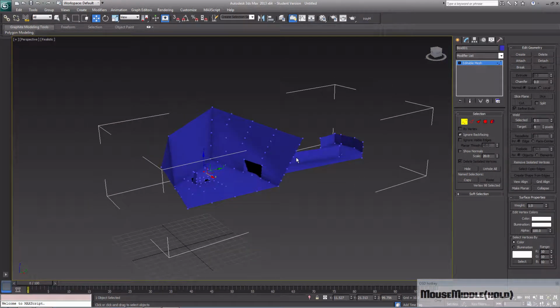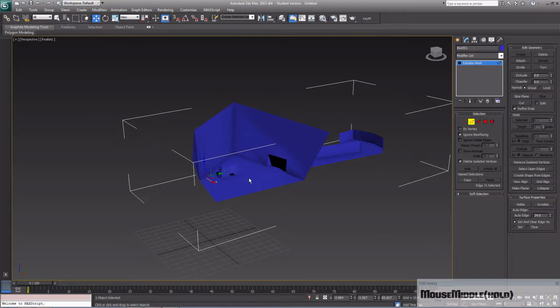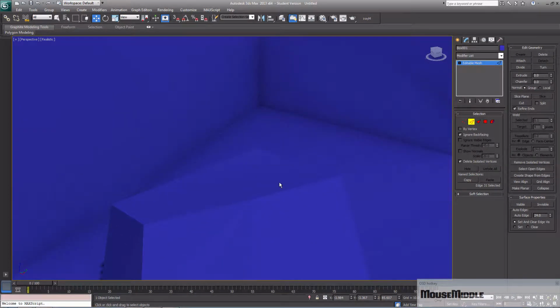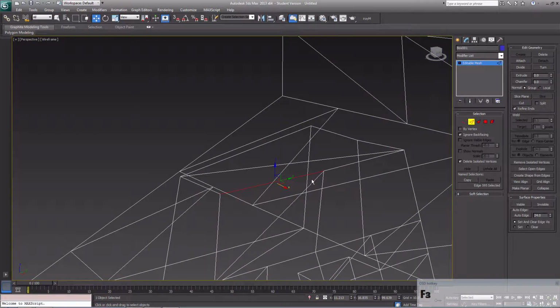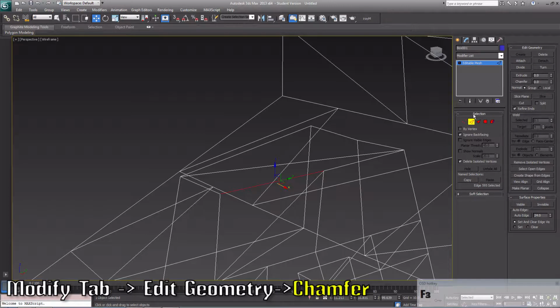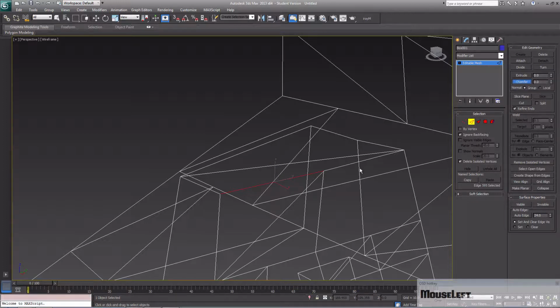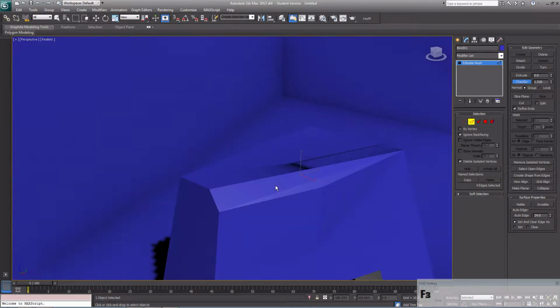Finally, this is a lot less terrain changing as it is for decoration, I find. But you also might want to, for some corners or whatever, chamfer your edges. And you'll see that instead of bevel, when we had polygon selected, when we have edge selected, we now have chamfer where bevel was. And what that's going to do is create two edges parallel to each other where that one edge previously was. This is kind of sensitive here. But you can see the effect it's having.